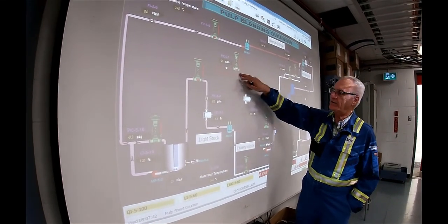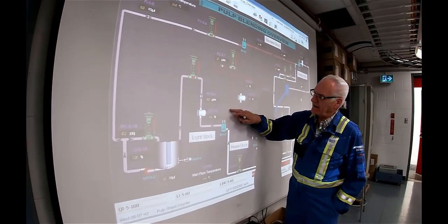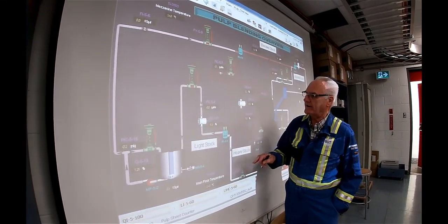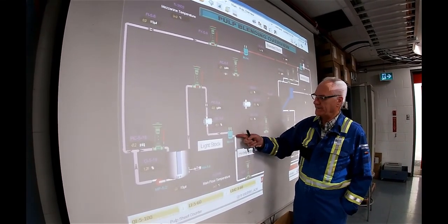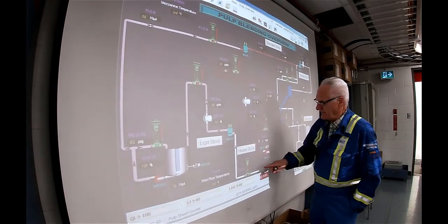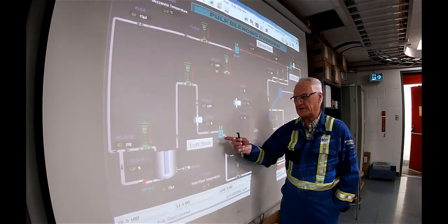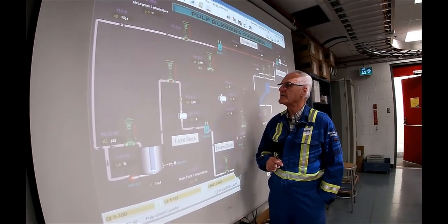Mari, would you go back to the overview, please? Overview is here. Just hit skip all. Then they're going to take 37.5 gallons a minute of water first, measured by this flow meter right here, and leave the white water valve on manual at whatever position it needs to be to give you 37.5 gallons.